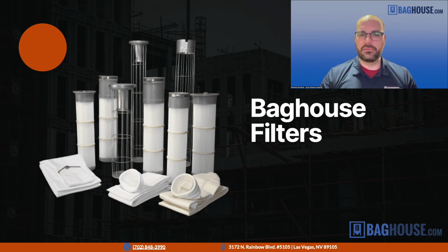Now, a very common, I'd say the three most common additives or treatments we put on top of the filter media. We take, if it's polyester, aramid, or fiberglass, whatever the base media is. Very commonly, we will apply on top something that is an acid-resistant finish. We'll also apply a hydrophobic, oleophobic coating that repels oils and waters. And then in many cases, where we need to collect a higher percentage of the absolute smallest particles, or if the material we're collecting, for example, is extremely toxic, highly regulated, whatever it might be, then we might apply on top what's called a PTFE membrane.